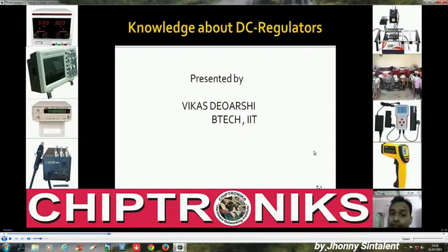Now, there are two kinds of DC regulator. We have seen while discussing the 3.35 volt regulator in the Lenovo Y570 that there is an LDO. LDO is low drop out, and that is a linear regulator. And we have seen the generation of 3 and 5 volts through switching on and off of MOSFETs, and we call that a pulse width modulation regulator. So why those two types of regulator? Why one linear regulator and why one pulse width modulation regulator, and what is the difference between them?